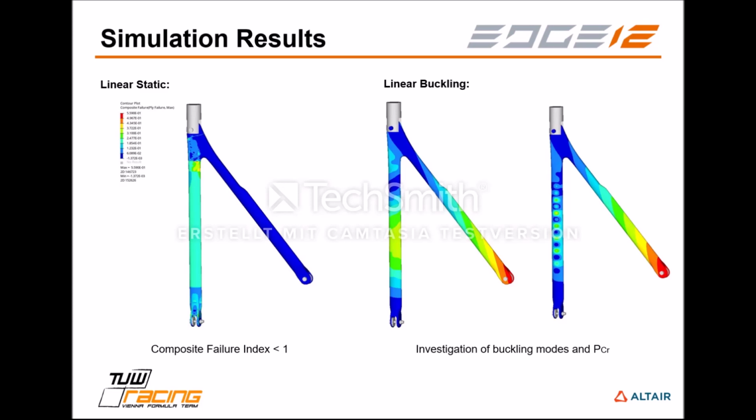Because if you look at our wishbone here, we have two arms of the wishbone. One arm is fixed into the test machine, so both ends are constrained. But the other arm is not constrained, so this end is allowed to move, and we should not consider that in our buckling analysis. So we need to find the buckling modes that are relevant to our application and define the critical loads after that.